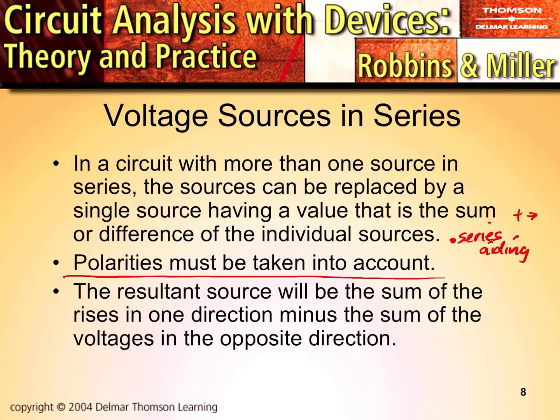Plus to minus, plus to minus for a series aiding connection, or you could have a series opposing. And if you were to have a series opposing, you would have plus to plus. And that would result in a potential that is working against the overall potential.